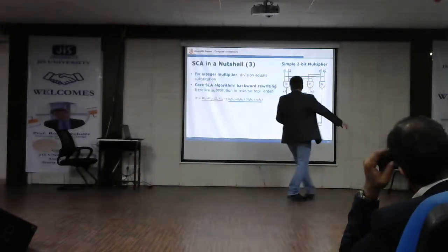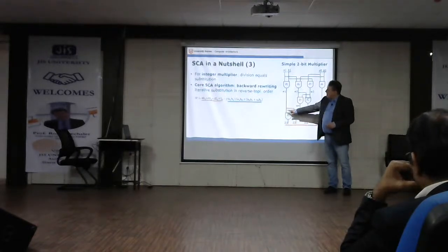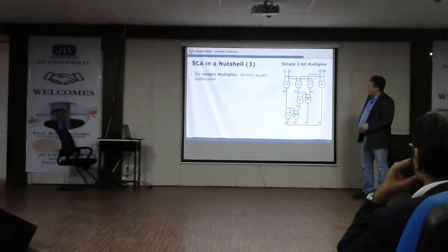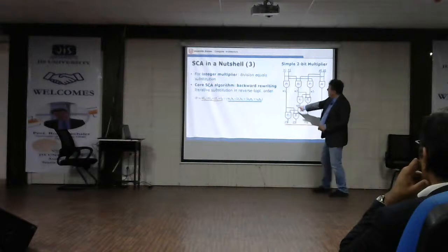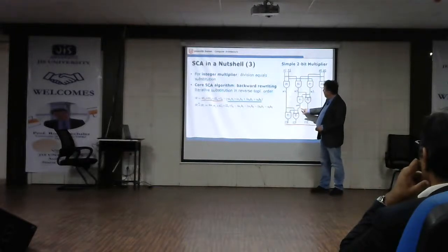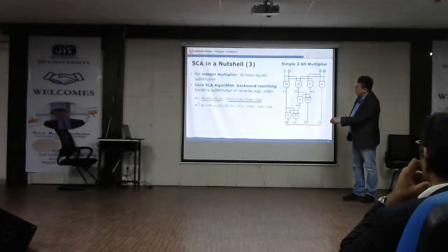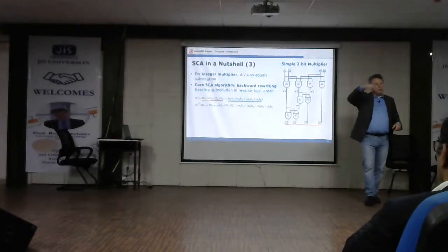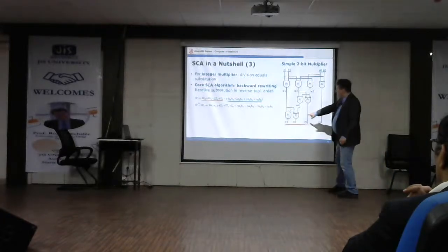And now we start here at the output with Z3. And we substitute this Z3 here by G1. So G1 is an AND gate. So we know that this is just a times b. And this means that it is substituted here with W1 and W4. Yes, and this means that we now substitute the Z3 variable by this value. Now we go step by step from the outputs to the inputs and substitute each of the values. In the next step, we would substitute this G2.